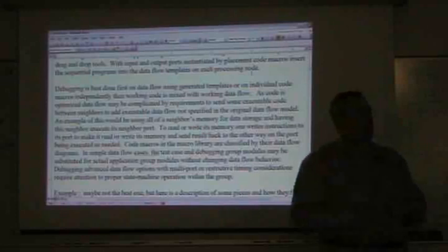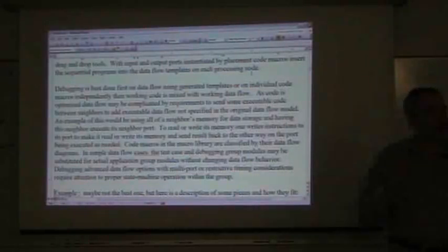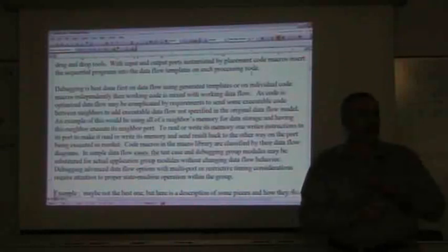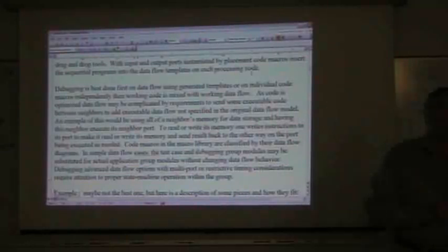And that node has a table of 50 values where an index into its table will return an SPI address and an SPI length. So I put originally 16 hex numbers in there. And my index was 0 to F. And if you sent 0 to F to this node, it would look up in its table and it would tell you the address where I had put the recorded sound for 1 or 2 or 3 in the SPI, and the length of that routine. And it would play it.